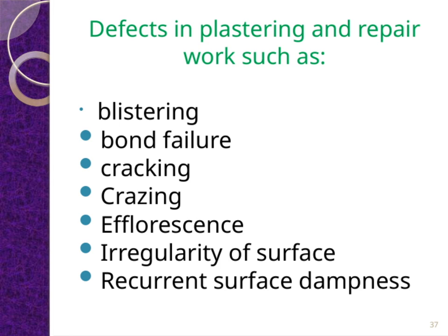Crazing refers to fine, interconnected cracks, usually on glazed surfaces or paints, giving a web-like appearance. Efflorescence is a white, powdery deposit on surfaces, resulting from soluble salts migrating to the surface with moisture. Irregularity of surface points to unevenness or roughness, which can be due to improper finishing or underlying issues. Recurrent surface dampness indicates persistent moisture problems, possibly from leaks or poor drainage, causing ongoing surface issues.